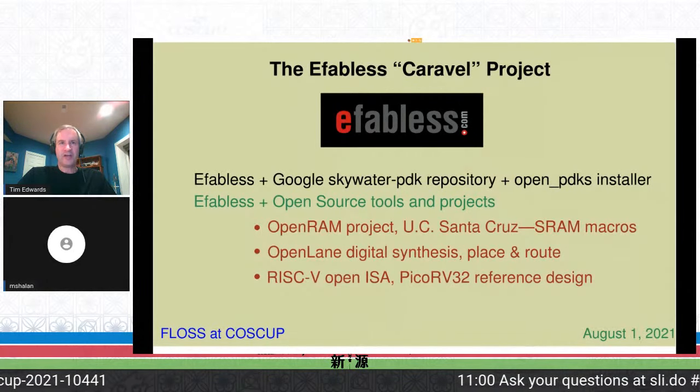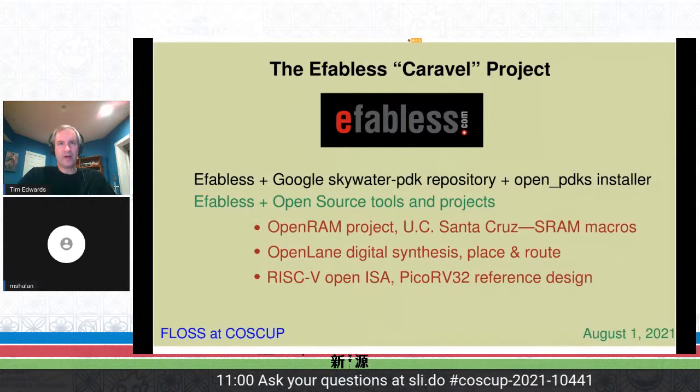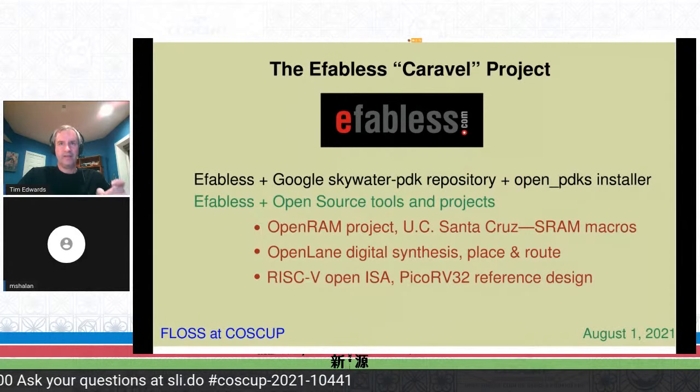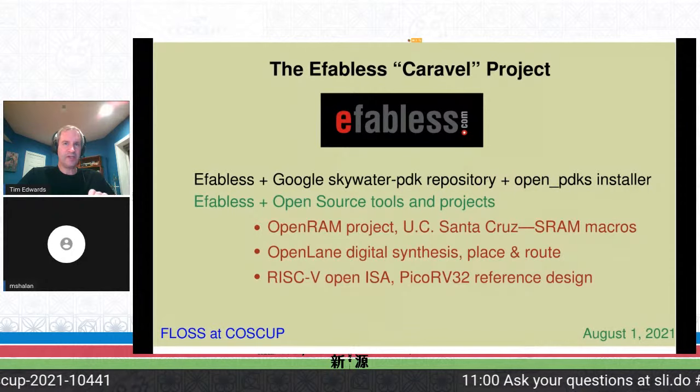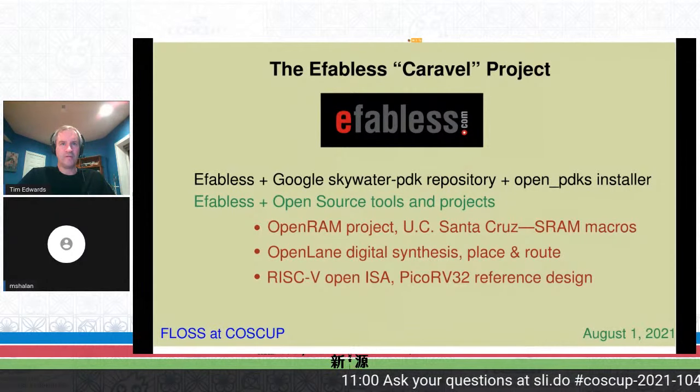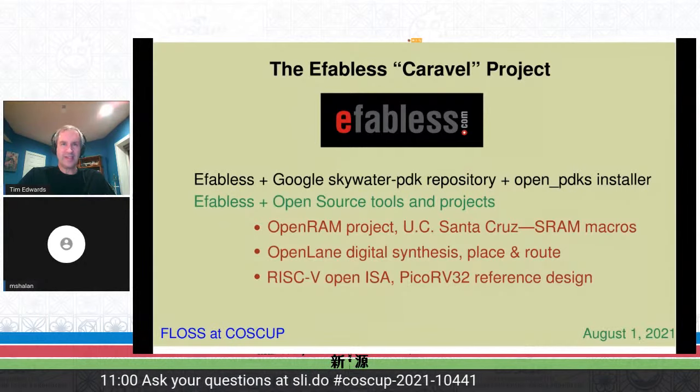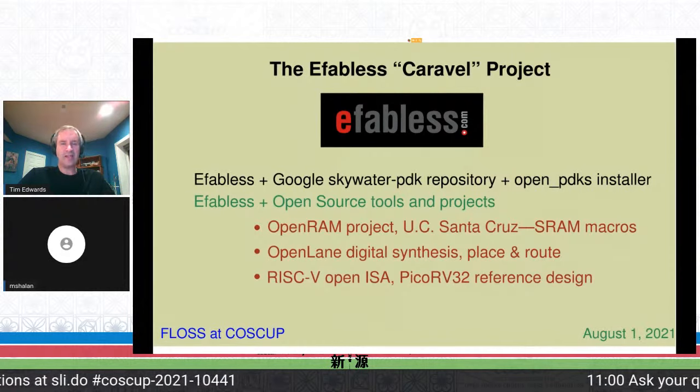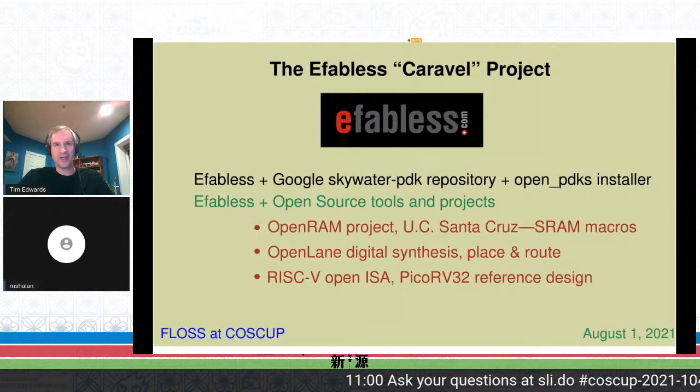The RISC-V project from Berkeley, which is now its own foundation, has really brought microprocessor design to the masses with an open source instruction set. The very simple and straightforward open source implementation of the PicoRV32 microcontroller by Claire Wolf isn't necessarily the best choice for custom chip hardware, but it is so well documented and easy to understand that it forms a natural backbone to any chip design project needing software control and communication with the outside world.